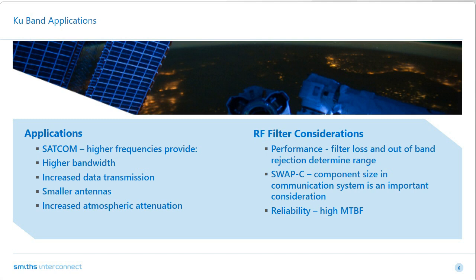Performance, reliability, size, and weight are critical factors with satellites. There are trade-offs that are mitigated with the system designs. The RF filter design has many options in this frequency band. Would the larger size of a cavity filter undermine the lower insertion loss and improved rejection? Could other areas within the RF chain compensate for some of the loss with a significant reduction in size and weight? I'm sure there are arguments for both options, and it likely depends on the mission, expected life, and budget for each satellite. Reliability is another factor that is mission dependent.